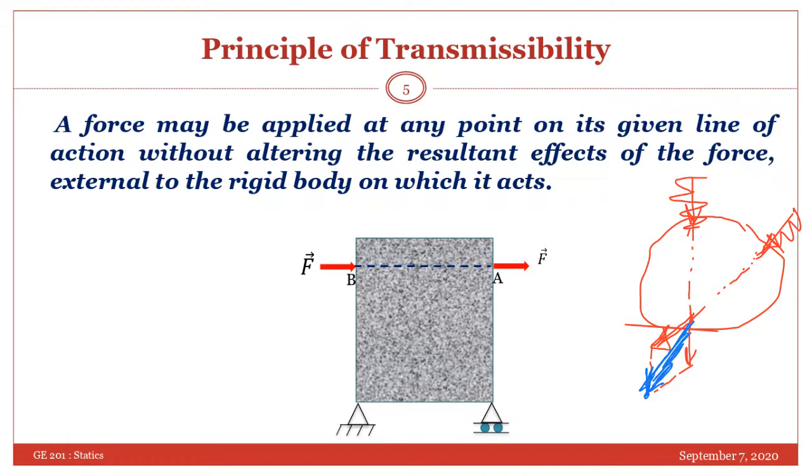So this will be the resultant. Okay, so this is by the help of the principle of transmissibility. By the help of the principle of transmissibility, you can apply the force anywhere along the line of action. The effect will remain the same. But keep in mind, this is only and only true for rigid bodies, not for deformable bodies.